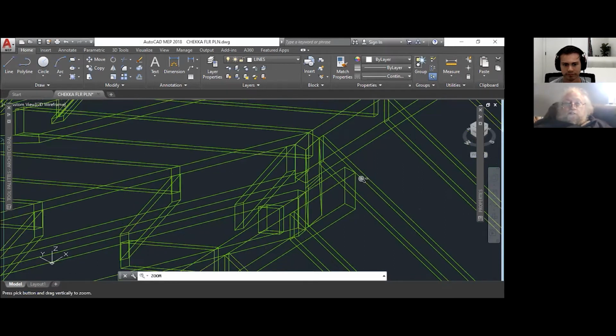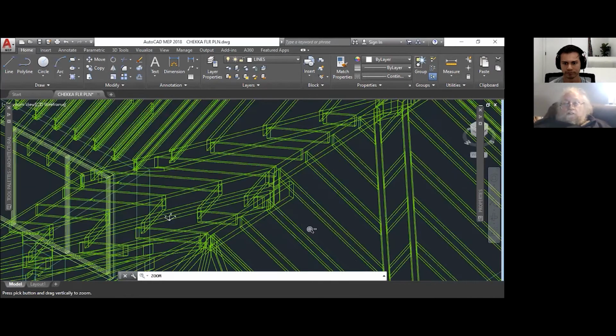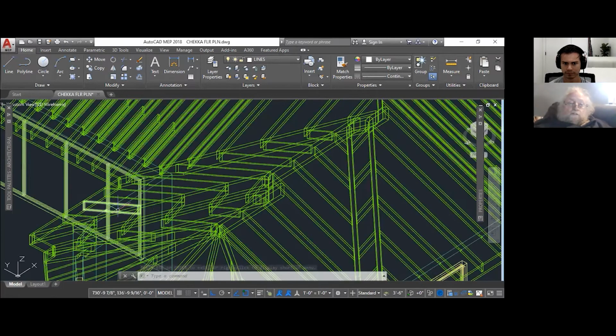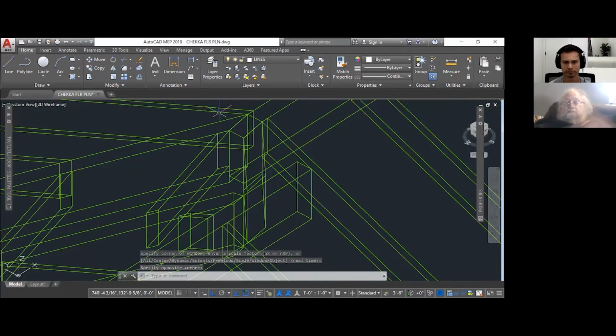What you have is two different spans here. You've got an 18-foot span from this wall to this wall down here, and then you have a 2-foot offset over here on this corner. So this 18-foot span has common rafters that have a specific run leading up to that ridge.